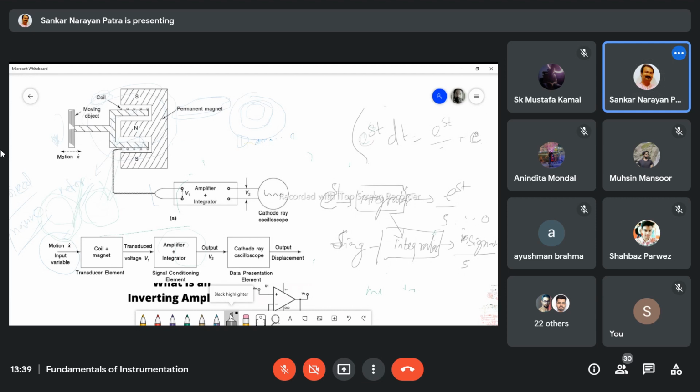In case of the integrator, if s is omega, then the signal is divided by omega. Now you increase the omega. What will be the value of the output of the integrator? It's getting lower. So when s is increasing, then the whole function will be decreasing.